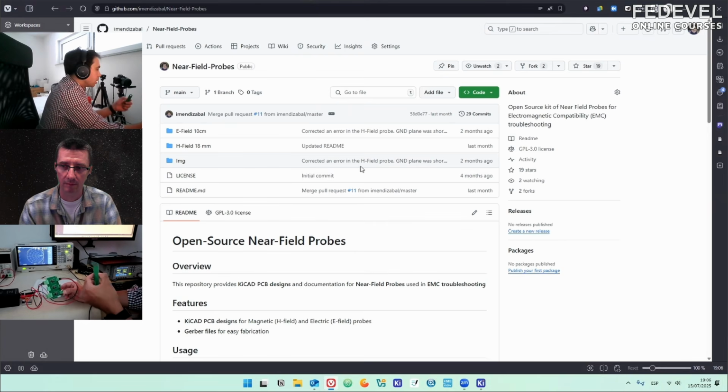The idea of this board was to design the DC-DC converter in all its range, to ensure that it could deliver all the power and all the current, no matter the load, and also to design the components. So I was evaluating different inductors, different diodes, and that's why this board was very handy to design the new version. And today we are going to use it to see what happens in the frequency domain